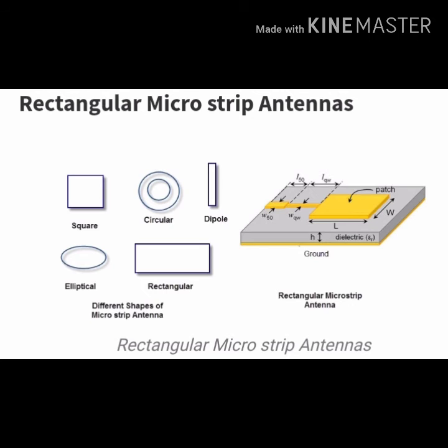Planar inverted F antennas. A planar inverted F antenna can be considered as a type of linear inverted F antenna (IFA) in which the wire radiating element is replaced by a plate to increase the bandwidth. The advantage of these antennas is that they can be hidden into the housing of the mobile when compared to different types of antennas like a whip, rod, or helical antennas, etc.